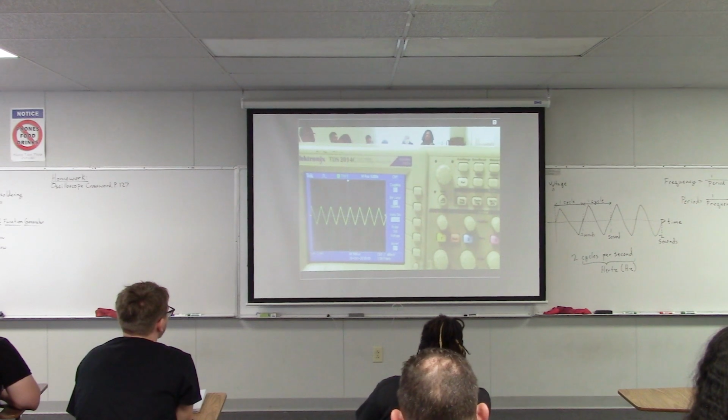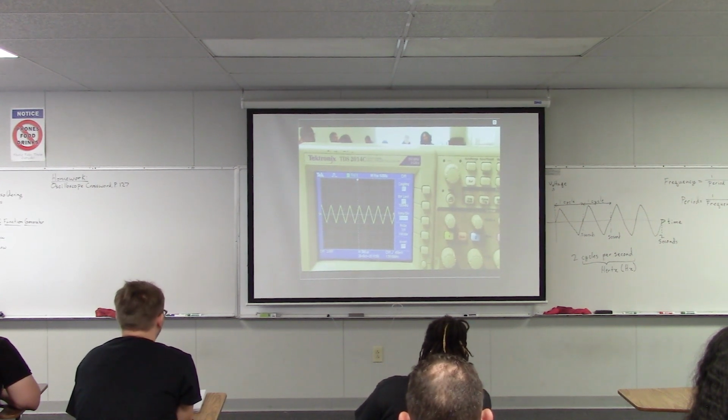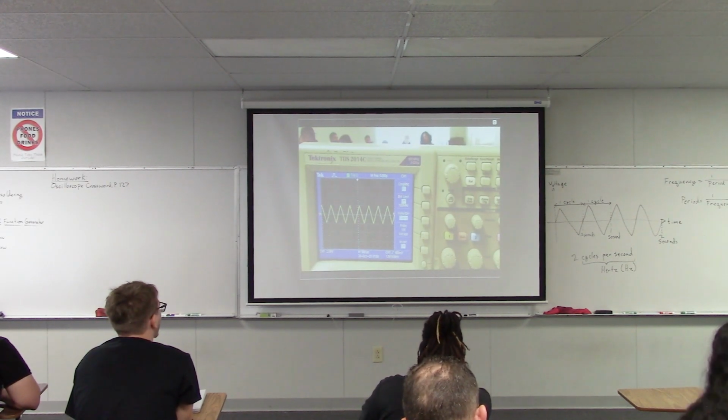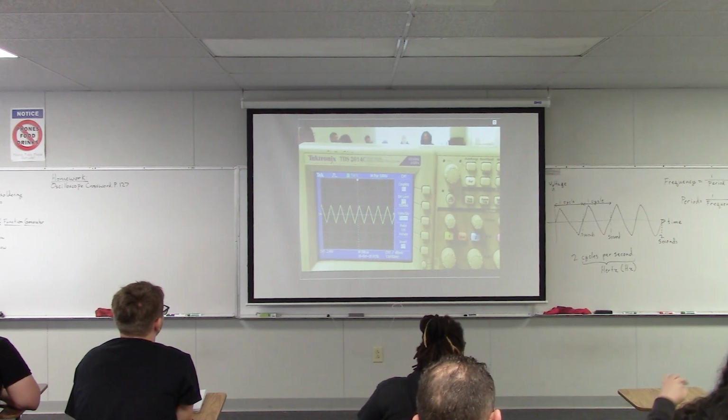But now this signal is looking kind of small on the screen. If there were details in that signal, it would be a little bit hard for me to see them. So I might want to zoom in on this signal to see it a little bit more clearly. So the way that I can do that, well, a camera only has one kind of zoom. It zooms in or zooms out. That's the only control you have. With the oscilloscope, you actually have 2 separate kinds of zoom. You could zoom in the vertical direction, up and down. You can also zoom in the horizontal direction.